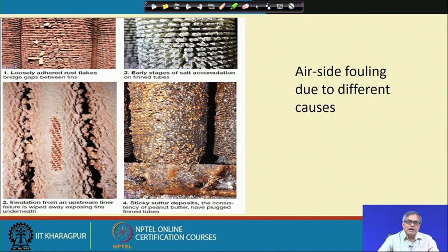If we go to the next slide, here is air side or gas side fouling for different reasons. These are again fin tubes, but not as has been shown. So, what could be fouled on this kind of fin surface? Let us say if combustion product is there, particulate will be there that will deposit on it. In the combustion product there could be some volatile gas which will condense, while the non-condensable part will go away, but those kinds of oil and char will deposit.